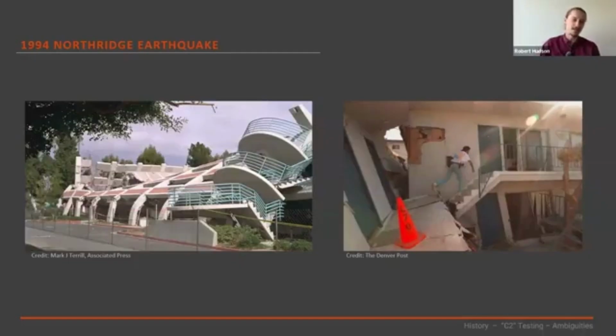So these are images from the 1994 Northridge earthquake in California. Actually a very large earthquake. The PGA in the highest acceleration area was about 1.8 G, which when we compare it to what Christchurch was, about 1 G, is a pretty drastic event. But believe it or not, prior to this, the industry was using monotonic capacities in uncracked concrete to design post-installed anchors in concrete, which I suspect we can all intuit isn't going to be appropriate for a lot of the design that we're doing for post-installed anchors in seismic regions in concrete.